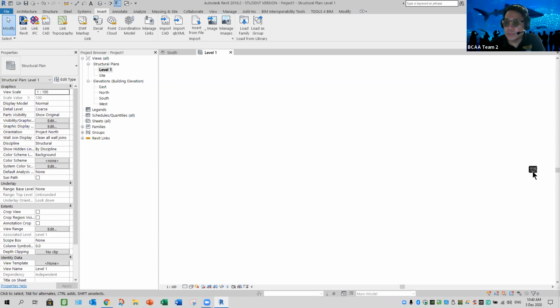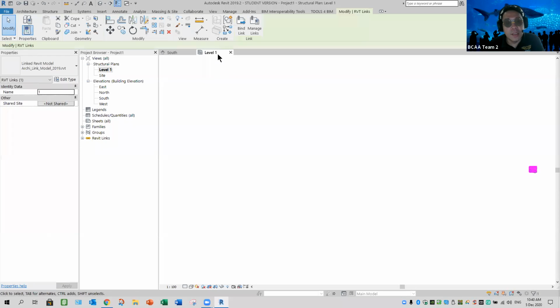Okay, so this one is inserted, right? If you can't select because of the link file here, you must uncheck. Highlight the link. Immediately you should pin. Okay, pin it, remember.